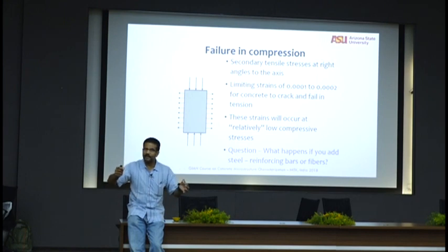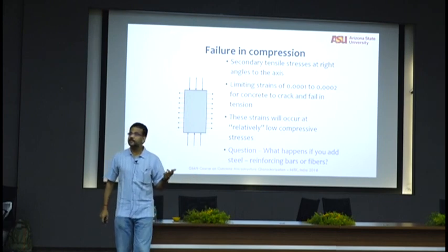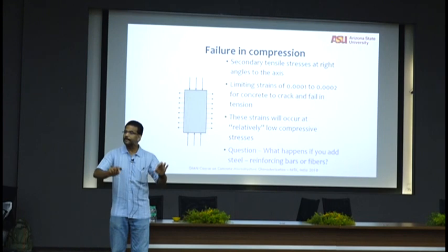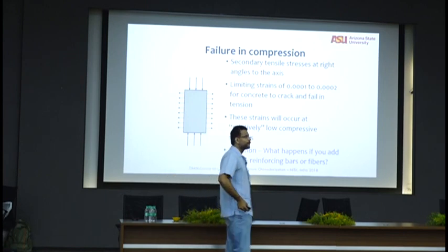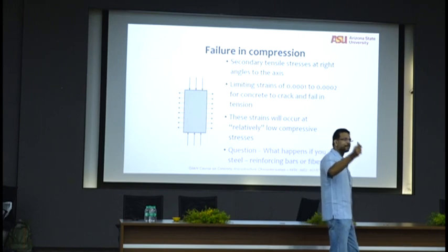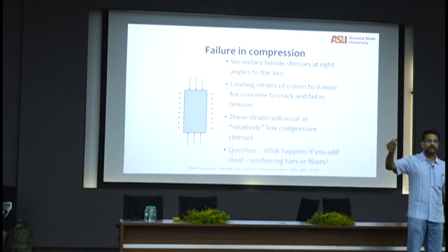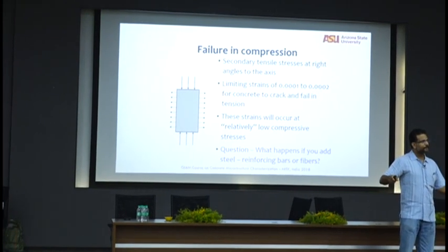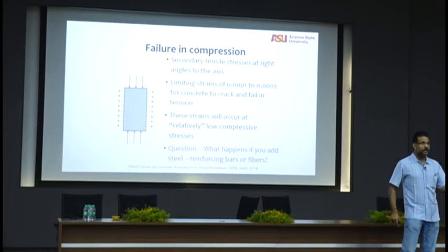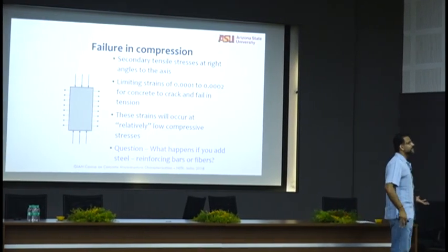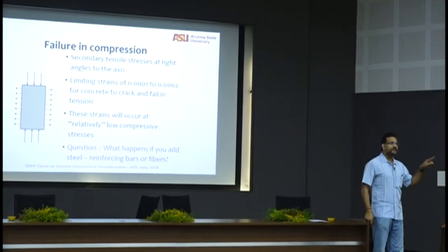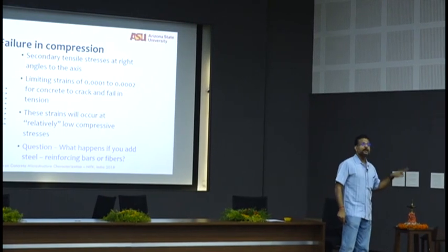See that? So when you have a localized crack, that area is not taking a load. What is happening is, the point next to it is taking a higher load, higher stress, which means that part is now stressed more. The chances of that part failing now becomes higher. That keeps propagating, and therefore microcracks propagate to form a macrocrack, and therefore it fails. So you need only a statistically probable crack that can localize and grow under a certain stress to fail your specimen. And if you have a bigger microcrack to start with, no matter what the strength in the remaining parts of the concrete are, no matter what the average strength of the concrete is, you will get failure. Therefore, failure is also a local property, which is very important.